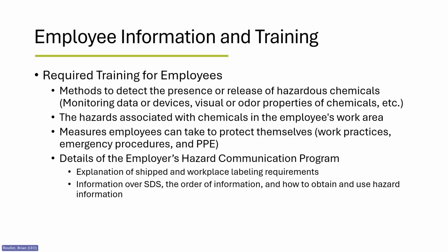The training for employees over the hazard chemicals they use must include the following. It must address the methods to detect presence or release of hazardous chemicals. This may include monitoring data or devices such as oxygen or carbon monoxide sensors, visual or odor properties, or other means used at the facility.